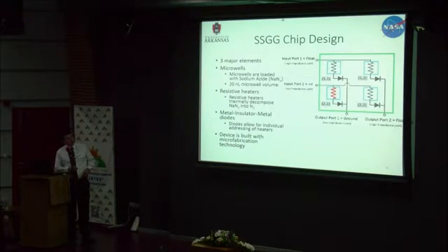So the microwells, represented by the blue boxes, are loaded with sodium azide. My prototypes are typically using 20 nanoliter volumes. Underneath each well is a resistive heater, which is made with microfabrication techniques. These are all built on Pyrex glass wafers. Nominal design size is 1 square centimeter at this time. Basically, the heaters warm up the sodium azide. Once it reaches about 325 degrees C, the sodium azide thermally decomposes, leaving behind sodium salt and creating dry, clean nitrogen gas.